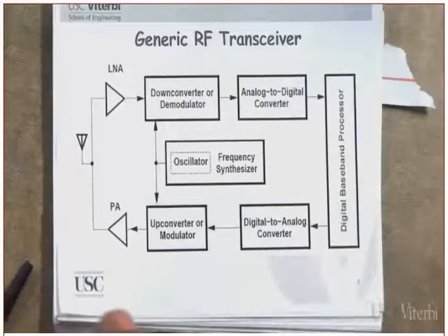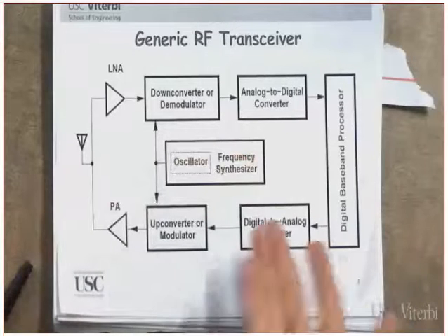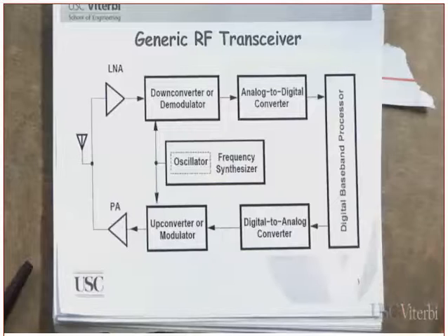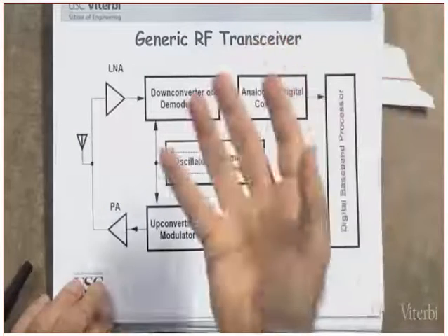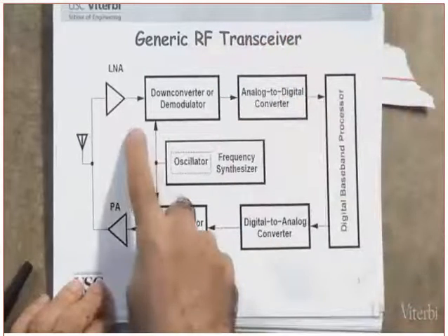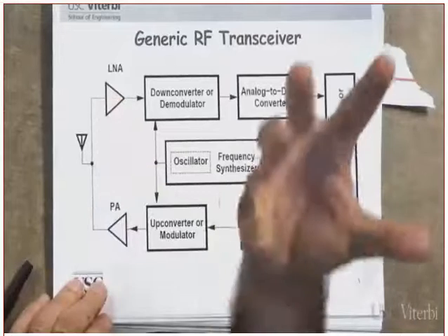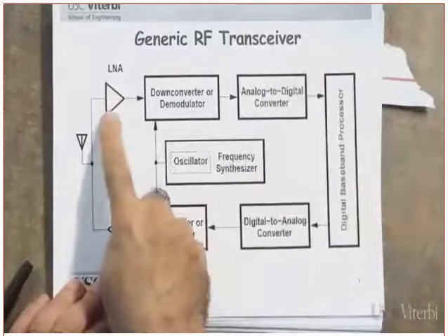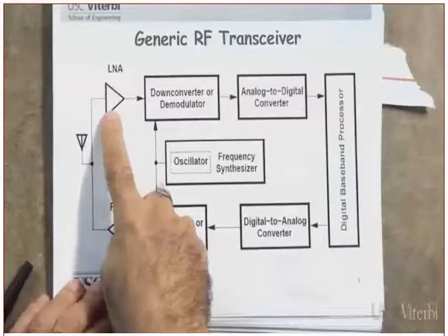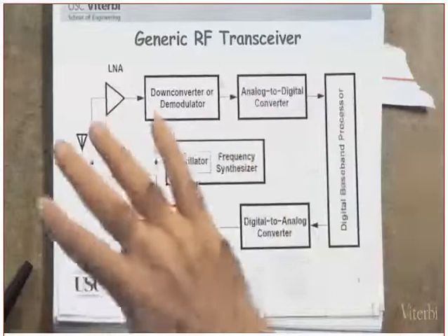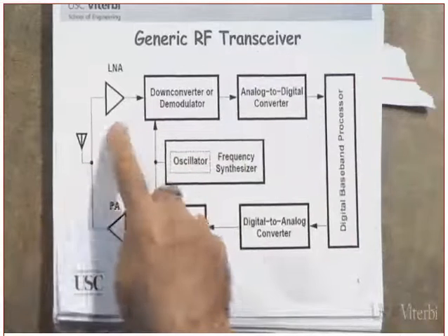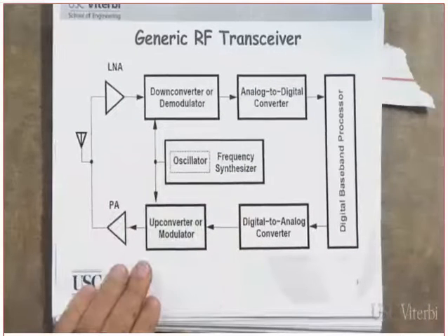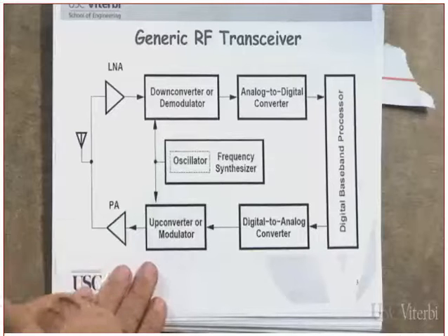Did you understand what I just said? They found it to be less than 5. Something must have happened. Why? Because the amplifier is going to amplify the signal and the noise the same way. There must be some noise which was added internally, because of the electronics in the device itself, resulting in the signal to noise ratio going down, degrading a little bit. Clear? We would like the device to add as small an internal noise as possible. We'll talk about that again in detail.